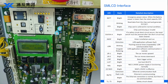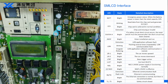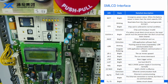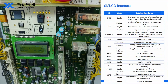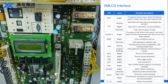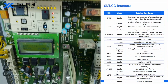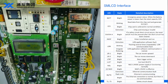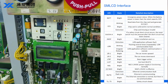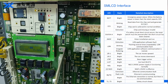Jack, I want to ask you a question. If the T4 and T5 lights are not on, can the elevator run? I think it cannot. Why? Because the door lock is not in place, so how can it run? Right. Henry is testing me. He is asking if T4 and T5 are off, can our elevator move or not? I said no. He asked why. I said because it means the car door lock is not locked. So how can the elevator run?